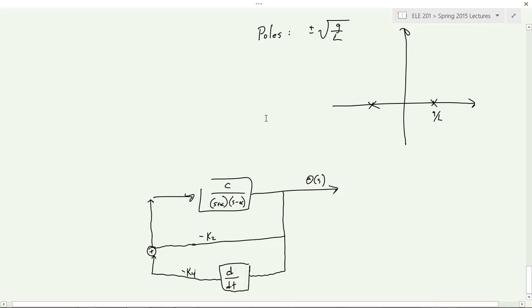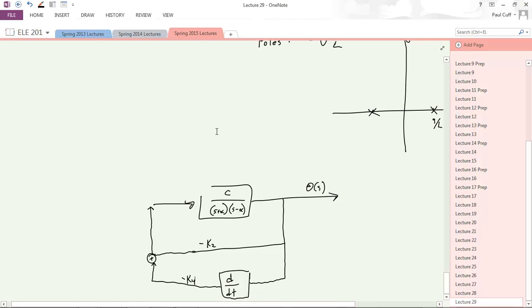All right. Feel free to come play with it. Yeah, you're right. They do interact with each other. The way I derive this outer loop, if I had more time, is you first just assume the inner one is perfectly stable, and just go control the outer one. But in fact, to correctly do it, you would take the transfer function that we derive. We have a transfer function for the balancing, and it does have poles. We've just moved them way over into the left half side. Those poles, when you then look at the outer loop that you're trying to stabilize, you have to take into account. And for example, if you try to center too aggressively, you might cause those poles to be unstable again. So if you take them into account, then you can make sure the whole thing's stable.